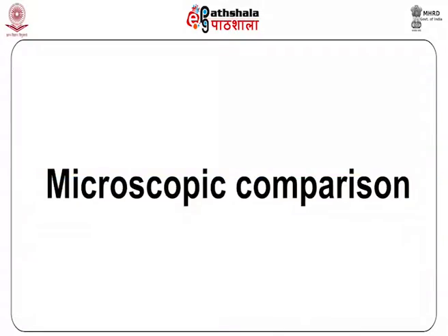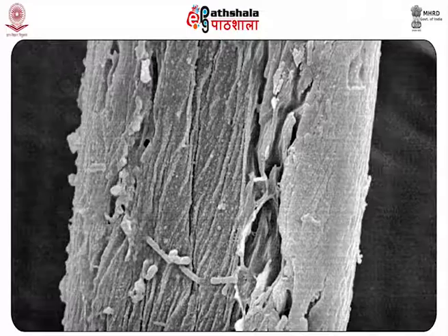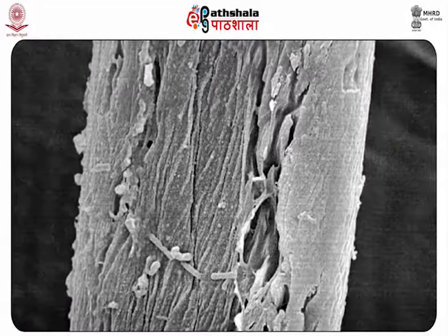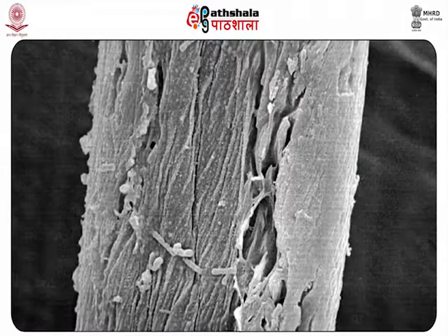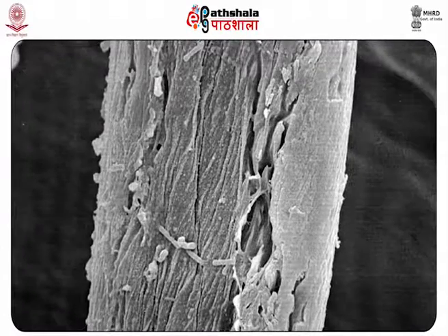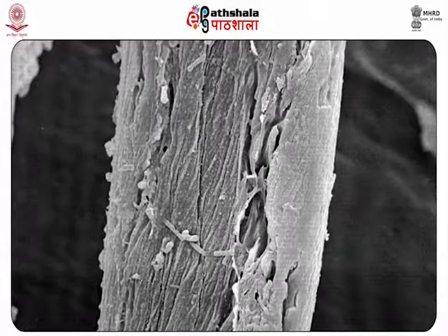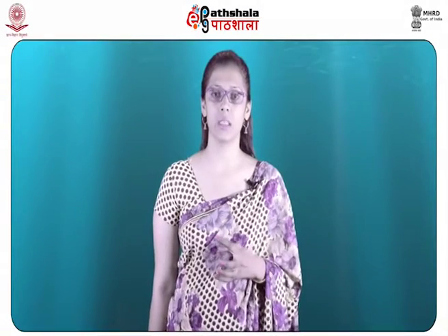Microscopic comparison. Microscopes having magnification of at least 100 power can be successfully employed for testing and identifying the fiber contents of a fabric. Microscopic test is very effective for testing natural fabrics. Difficulties can be faced while testing synthetic fibers, as many of them have similar appearance.